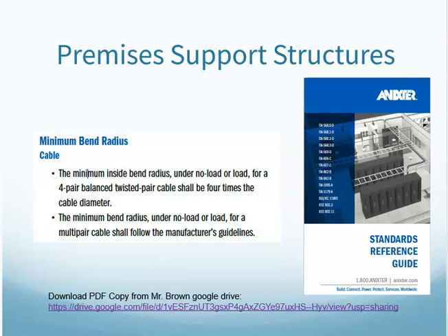If we bend cabling too tight, the wire twists in there, we deform those so that the cancellation may not be happening at that little point in time, and I'm going to get interference where that bend is. If I keep bending, I might actually damage the cable inside.